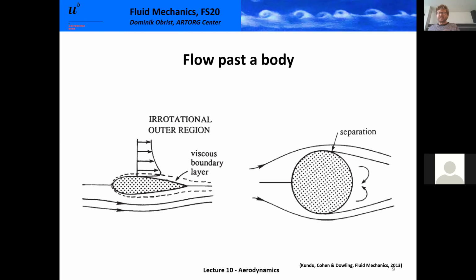So let's try to understand what is happening with the pressures in this wake. Or maybe let's first take a look at the pressures at the leading edge of this object, of the cylinder. Well, if we're sitting on the streamline directly in a symmetry plane of the cylinder, the streamline will end at the point that is also known as the stagnation point, because this is exactly on the symmetry point, the velocity will go towards zero.